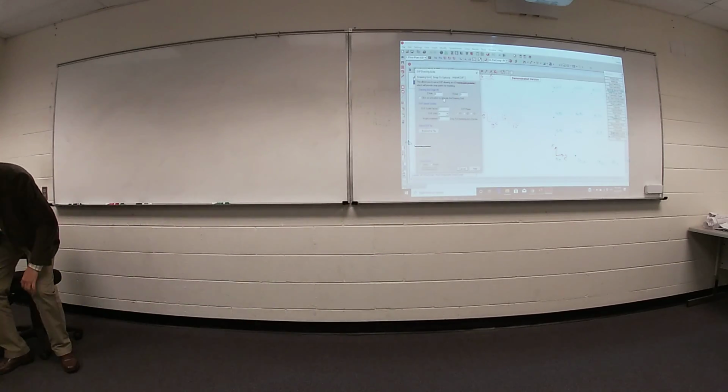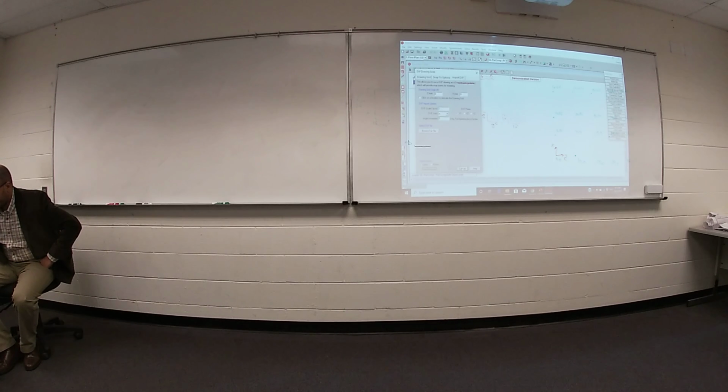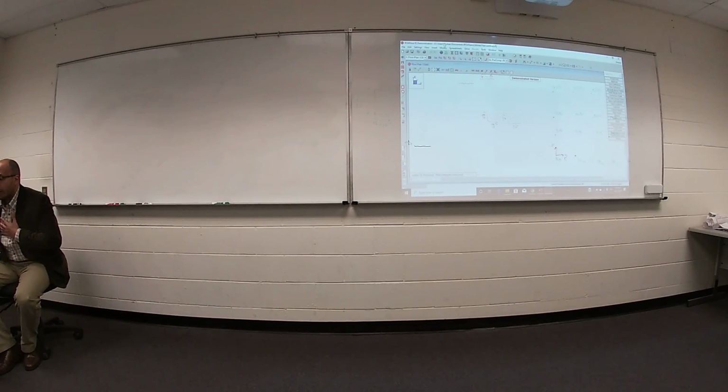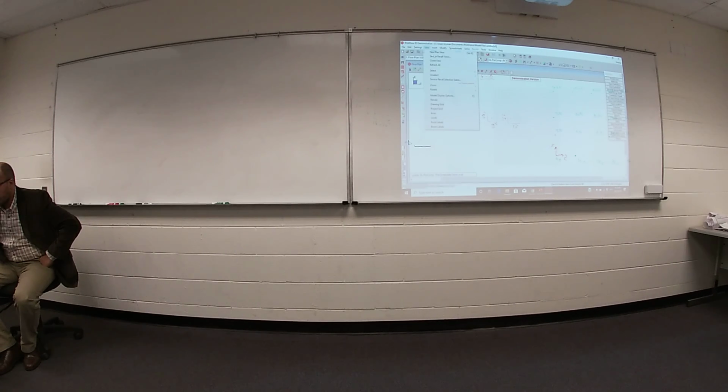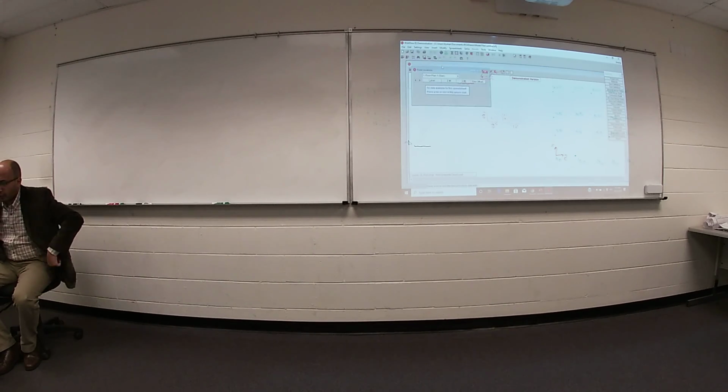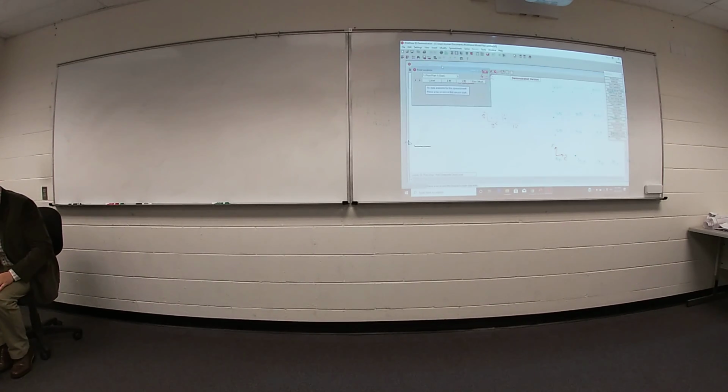So I will not use this grid. I will do my grid lines by myself. If you would like to remove this one, go to view, drawing grid. First step: insert, point. I will do my points one by one.